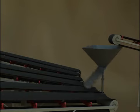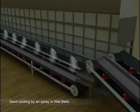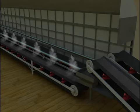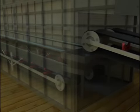The rotary feeder mechanism directs the aggregates flow to the respective conveyors and subsequently to the hoppers in the wet belt system. Hereon, all the facilities are covered and insulated to avoid heat loss. The conveyors carrying aggregates of size 10 mm and sand pass through a chilled air blast, while larger aggregates pass through wet belts with chilled water spray with temperature of 2 degrees centigrade.